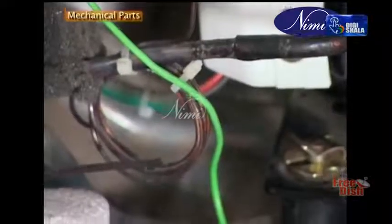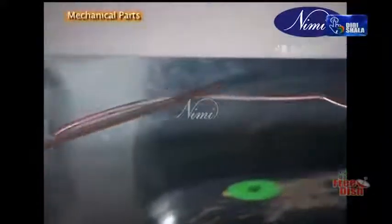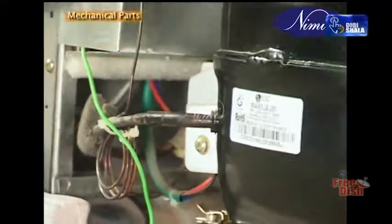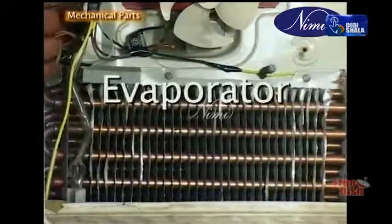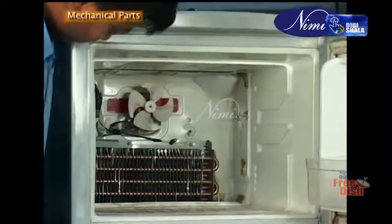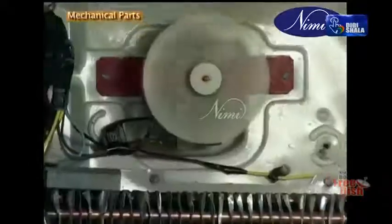It meters out the required amount of refrigerant to pick up the heat from the evaporator. It consists of a long, small diameter copper tube as the liquid from the condenser is pushed through a small passageway. The friction between the refrigerant and tube causes pressure drop. Evaporator. Low pressure and low temperature refrigerant enters into the cooling coil to evaporate to produce low temperature and changes